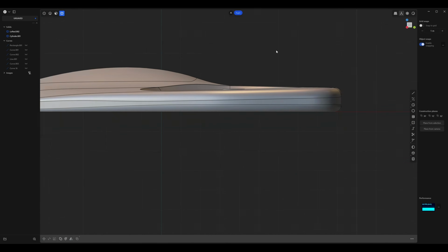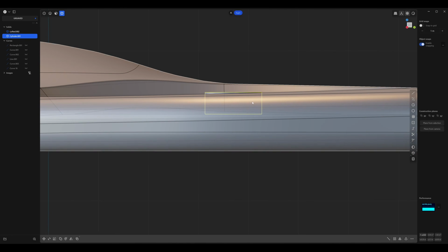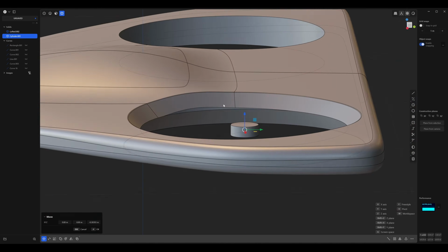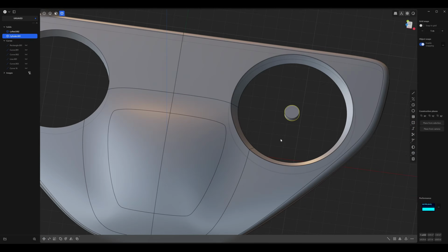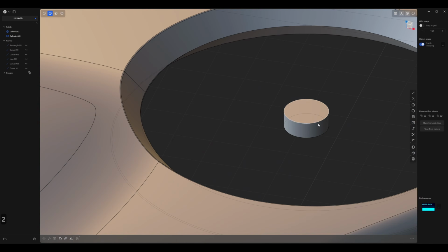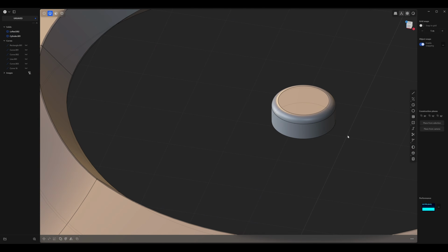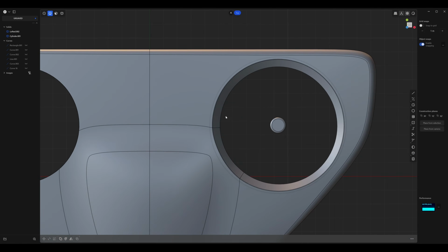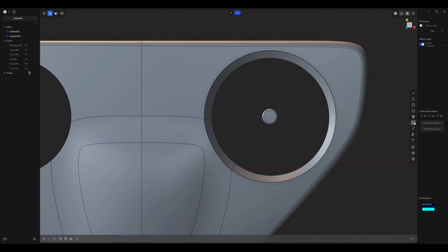Let's go to the right view, turn on X-ray view. And let's just place it maybe a little bit lower. You might have to adjust this once we create the propellers, but for now, this looks pretty good. Go ahead and give this a bit of a fillet as well. And let's go to our top view. Next, we're going to create a propeller arm or something that will support this attachment. So click on center rectangle and let's just create a little rectangle here.